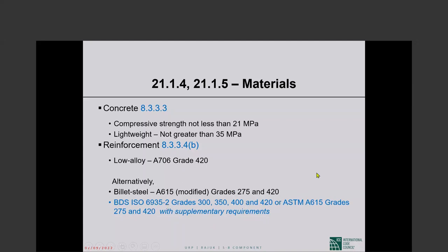There is a higher grade reinforcement available and in use in Bangladesh, but that cannot be used for members of the lateral force resisting system of a structure assigned to design category D, as we discussed at length on that first day. Okay, you can look back to that slide set or your notes.